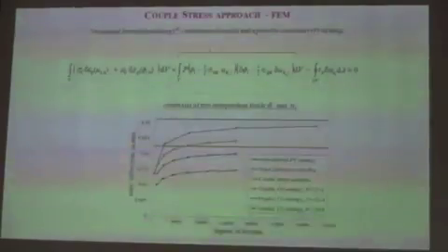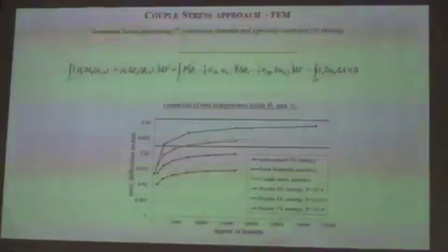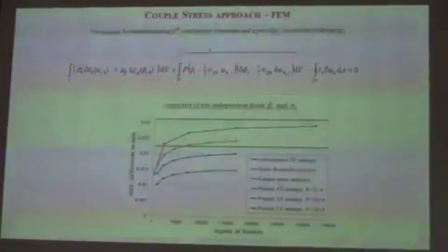So this is why you can use C0 continuous elements, and in a penalty constraint term that you add in this energy, you will force somehow the rotation to be like the macro rotation vector. And this is, of course, a constraint of two former independent fields, phi and u. But now you have the choice for P to build up this error.